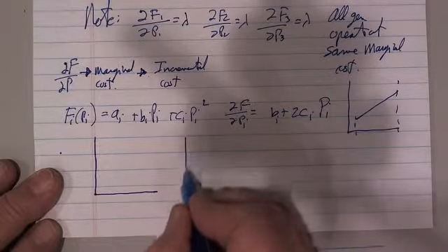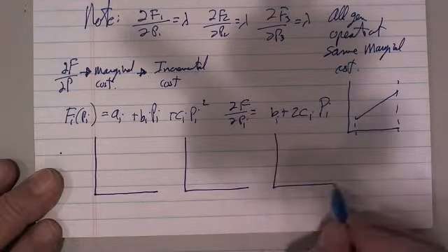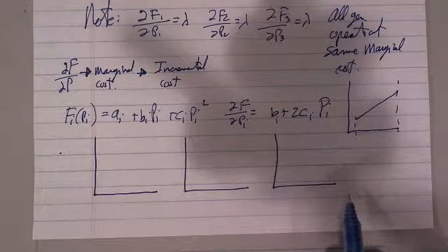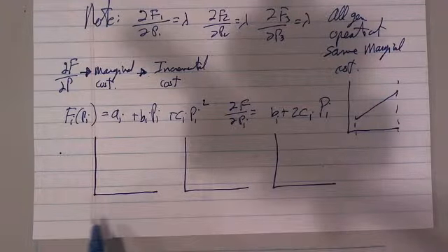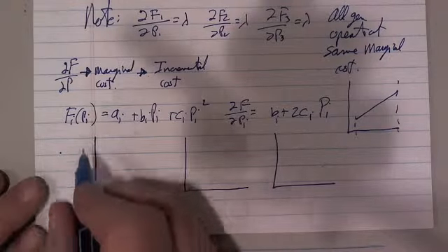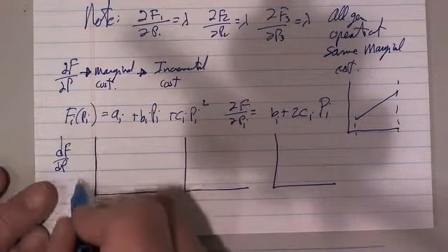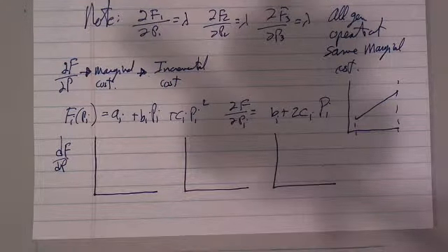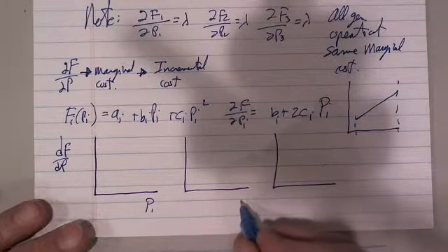the incremental cost functions for our three generators on three pieces of graph paper, and I lined them up on a table. Let's say I taped them down, and I made sure that the zero points were all lined up horizontally, and that the df/dp scale on the vertical axis was the same.